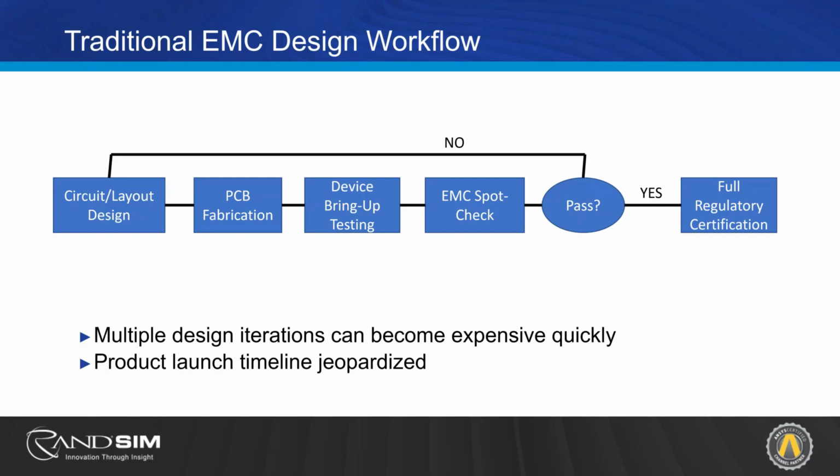So say you're taking your EMC tests, everything's passing, going fine, and then you get to a radiated emissions test case and you fail. If this is your official test, all of the previous data has become invalid because now the change that's required to pass radiated emissions is no longer representative of the device that had passed the previous tests.